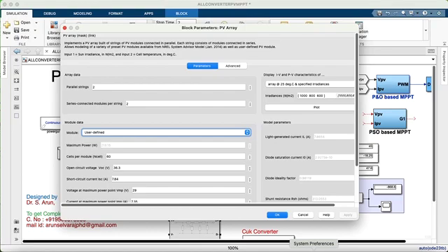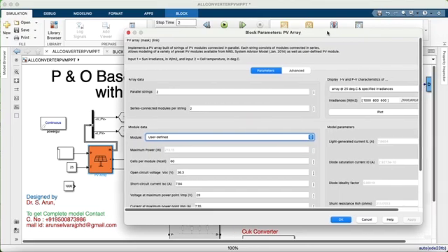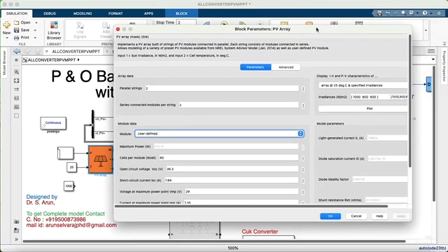There are two steps involved. One is perturb and the other one is observe. Perturb is nothing but introducing a small change to the PV module, such as increasing the array operating voltage to cause its power to vary. The second one is observe. Observe is nothing but periodically measuring and comparing the PV output power to the previous one.